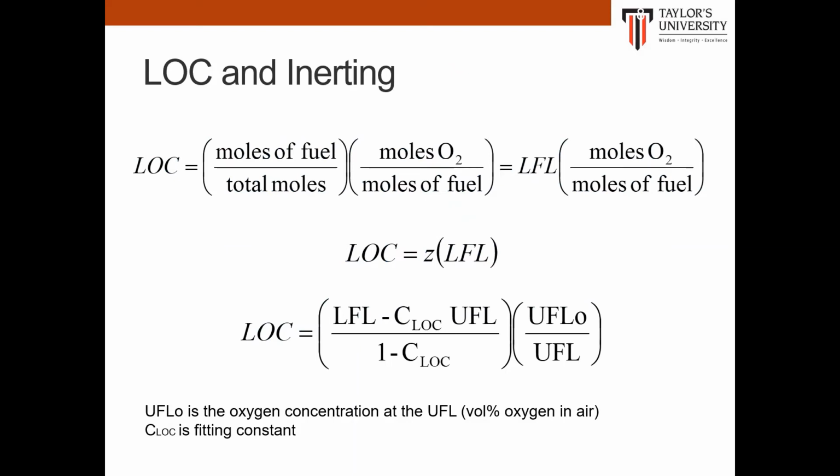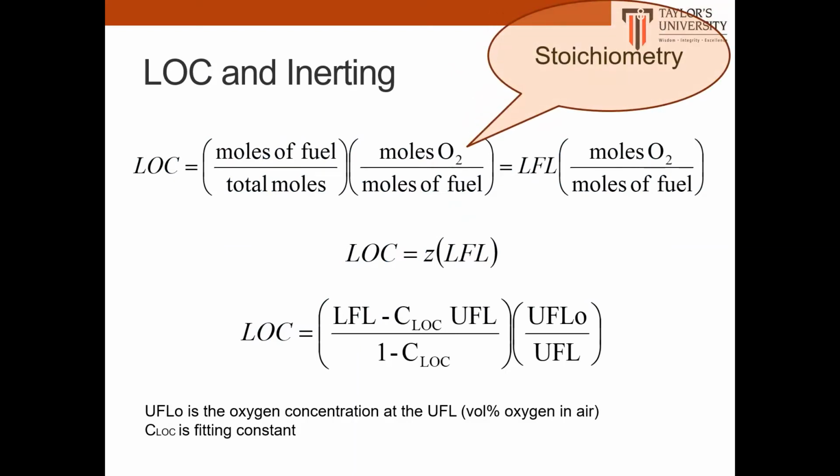The following equation shows the LOC calculation, where it starts from the moles of oxygen from the stoichiometry and the moles of fuel. In other words, it is the LFL times the total moles of oxygen over moles of fuel. So you can see from the equation down here that LOC equals this whole thing, and you can just plug in the values.